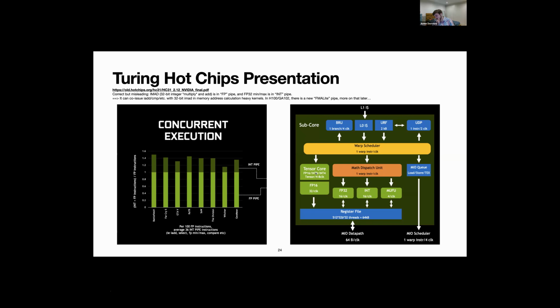Another thing that's interesting to point out there at the high level is that the trend in Hopper has been to do bigger instructions that do more automatically, outside of DSM and regular instructions. So a TMA instruction will do a huge amount of work in what's, in theory, a single SASS instruction. In practice, there's a whole bunch of overhead before and after. Same thing for Hopper tensor cores, where one instruction will take many cycles. And so they're effectively avoiding this warp scheduler bottleneck by having bigger instructions that do more work. But if you're running vector workloads, non-tensor core workloads, that bottleneck is still important in my experience.